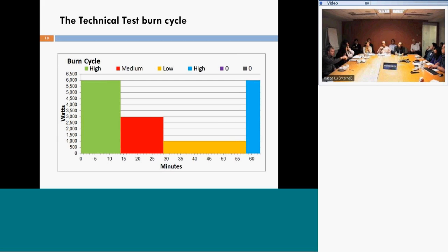So how do they do it? Could you describe how they... Well, most of these stoves are just sticks. You feed sticks in or pull them out. The more you feed in, the higher the power. The cooks in Central Java are very highly skilled at running this and actually put in the fuel that they know will burn down slowly. It's considered a highly appreciated attribute of a stove to put in just the right amount to get the power you want, and that it should turn itself down. They will walk away knowing that the stove will do exactly that and not burn the fuel. When they come back, the food is there and they can keep it at low power. LPG can't do that. There's a reason for people to like that feature.